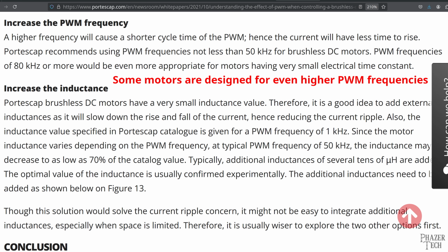That's why the ideal PWM frequency for motors is anything above 20 kHz, which is the upper limit of what the human ear can detect. For example, 25 kHz is a common PWM frequency since it isn't audible, but not all motors will respond to such high frequencies, especially budget motors. Unfortunately, not every motor will include this specification, in which case you'll need to determine the optimal frequency by trial and error. So that covers how to control the speed of a motor, but what about changing direction?